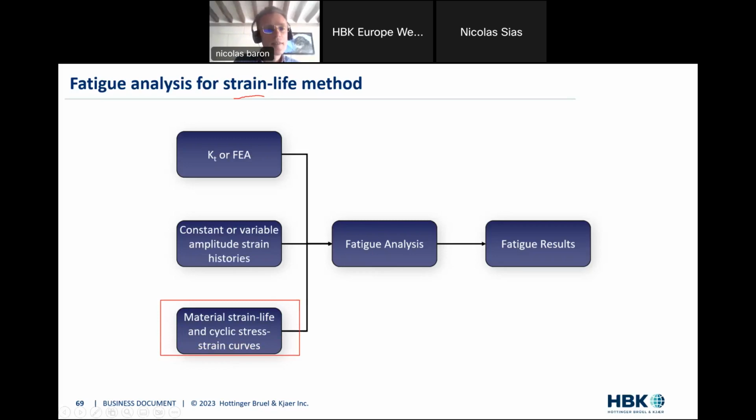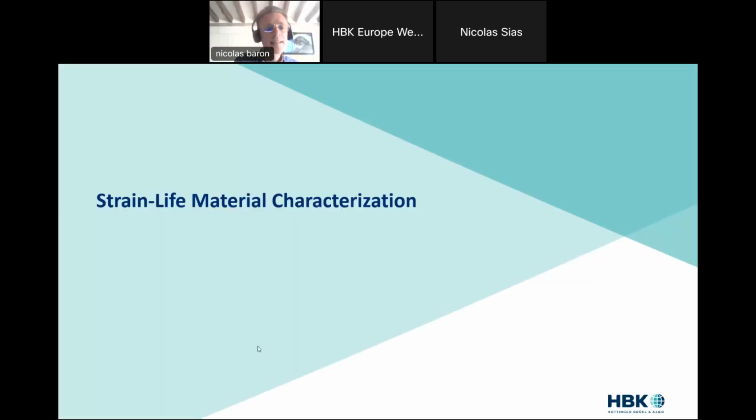Remember, before we used the SN curve for the stress life method. Now we're going to use another kind of curve, which is really dedicated for strain life calculation. So this curve is a bit different than the one we've seen before. It's a bit more involved. Let's see all together how you would characterize your material for having the strain life methodology in mind.